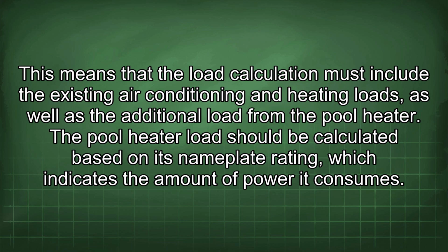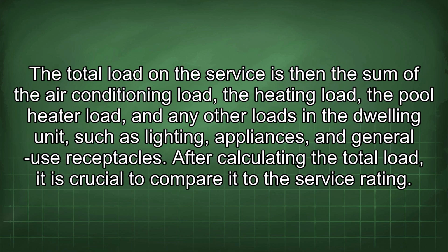The pool heater load should be calculated based on its nameplate rating, which indicates the amount of power it consumes. The total load on the service is then the sum of the air conditioning load, the heating load, the pool heater load, and any other loads in the dwelling unit, such as lighting, appliances, and general use receptacles.